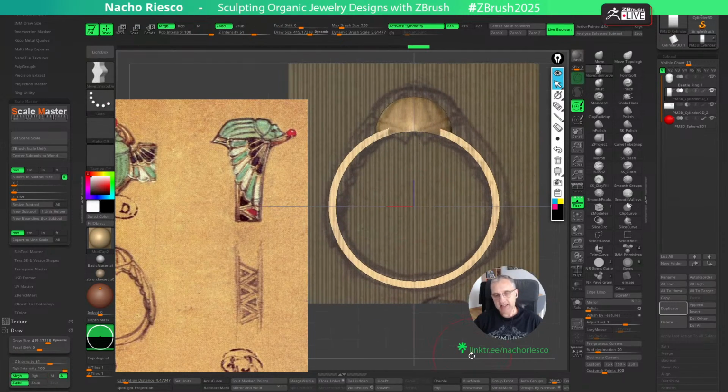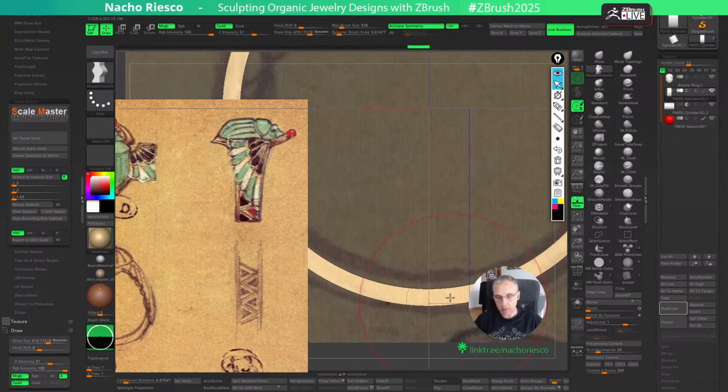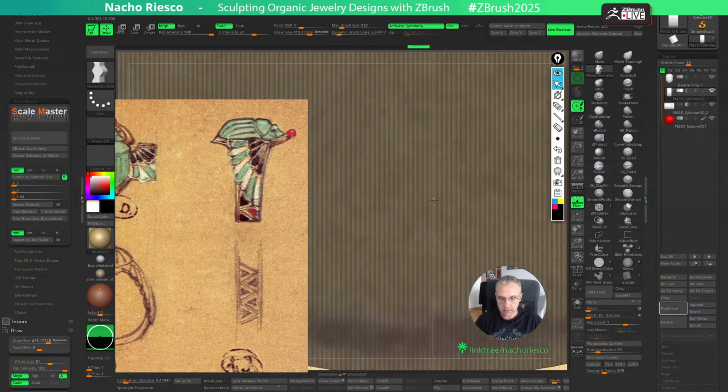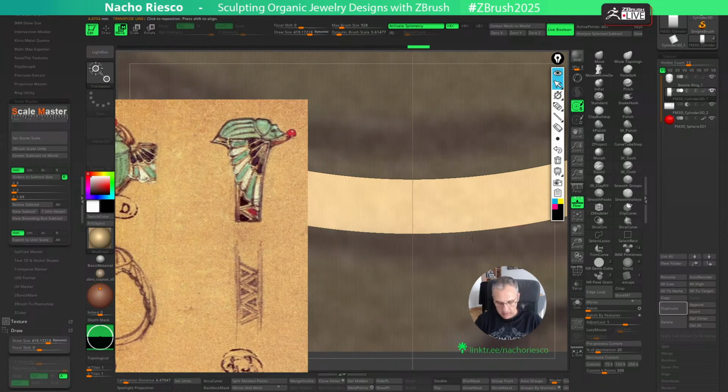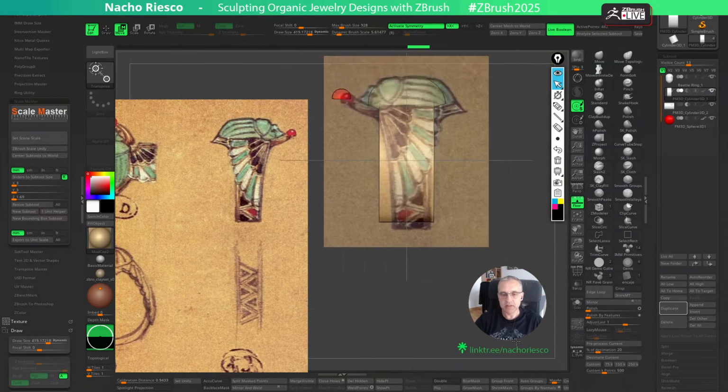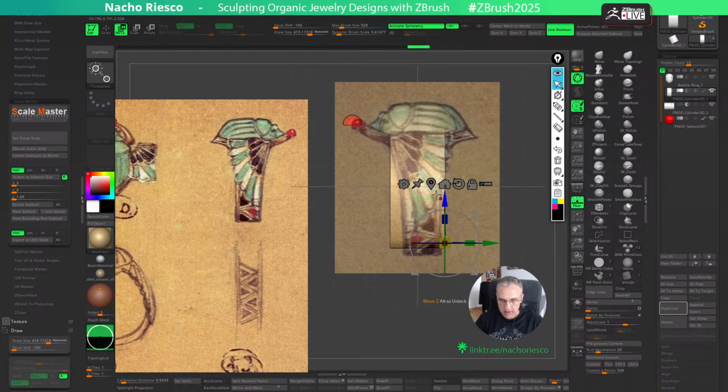Maybe now at this point it's a good moment to check how thin this is. Let's zoom in here with the transpose as we did before, from left to right. Here we are creating a shank of thickness 0.9433 millimeter. That means that the volume we are making now is less than 1 millimeter. It doesn't make too much sense, so we should make it bigger.